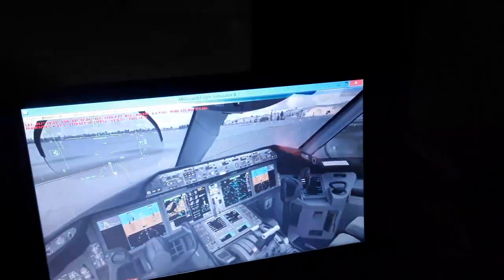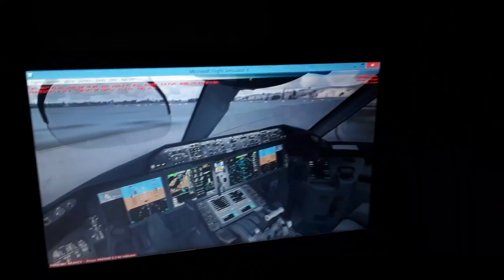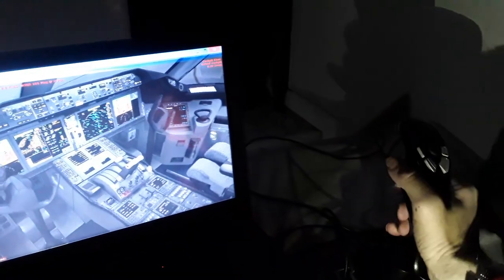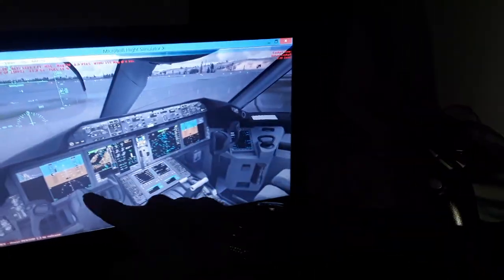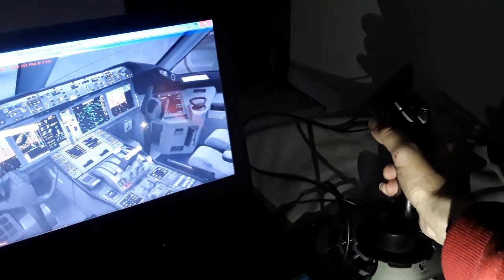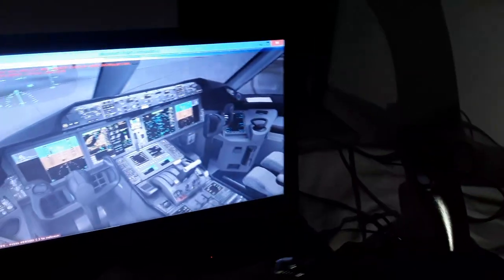It's this way. You open up this red guarded switch here. So also you can see the flight control computers again here. This switch. Fly-by-wire aircraft. So you have the side stick deflection, both sides, the captain and the first officer, they move together. As you can see, they're interconnected in flight. All functions, you use the control column for climb and for descent, for moving the elevator of the aircraft, for climb, moving up and moving down.